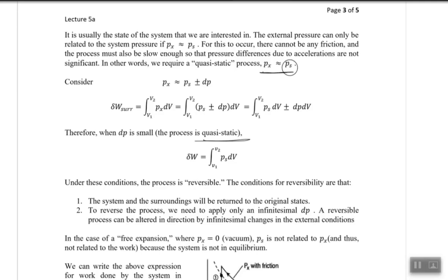should be equal to the change in pressure outside the piston. For that case, the process must be frictionless and the process must be slow. In other words, the process must be a quasi-static process. Quasi-static process means whatever small change in pressure can be altered, or let's say negated, and that means this can be equal to this now.